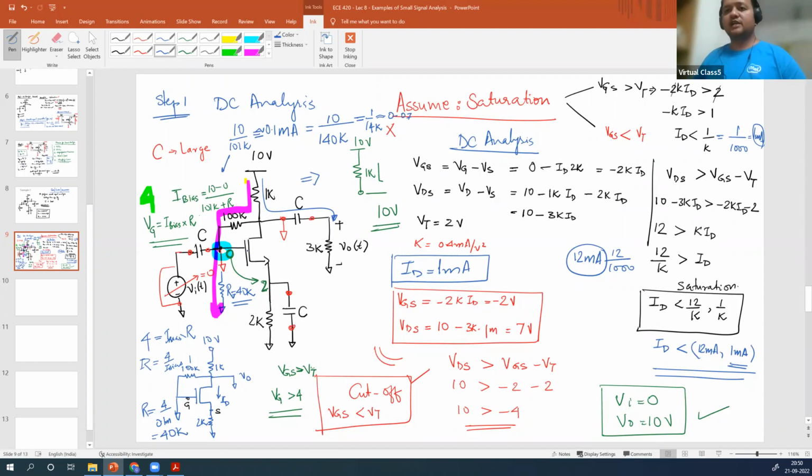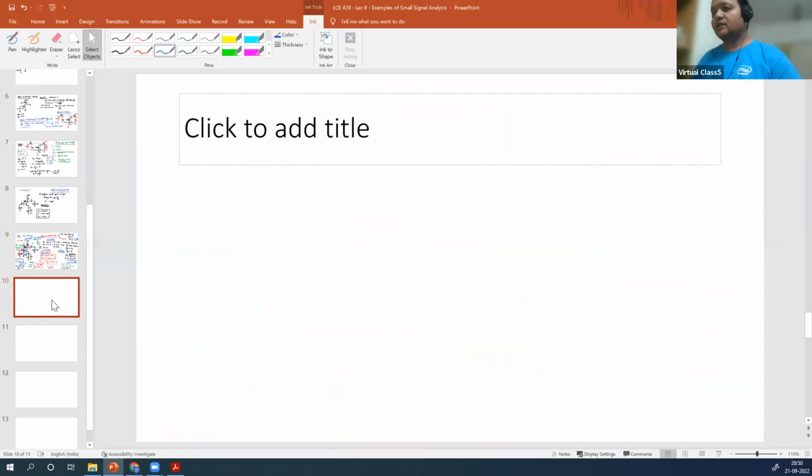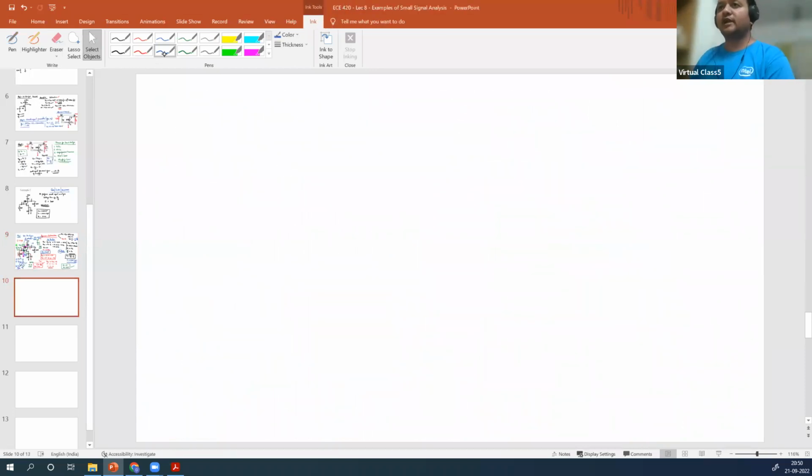You remember we talked about what overdrive is. Remember, you have not even done AC analysis yet. You are still in DC. You need to find the DC operating point here. So this is going to be practical. In this particular case, if you want an overdrive, that is VGS minus VT, of 0.1 volt equal to 100 millivolt, then what will happen?